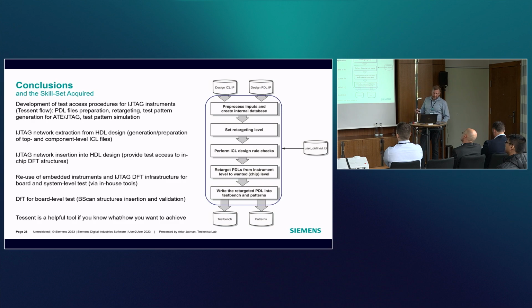You need to do the IJTAG network extraction from the HDL design, both for component level ICLs or ECLs and the top level ECLs. Then you need to know how to perform IJTAG network insertion into the HDL design.